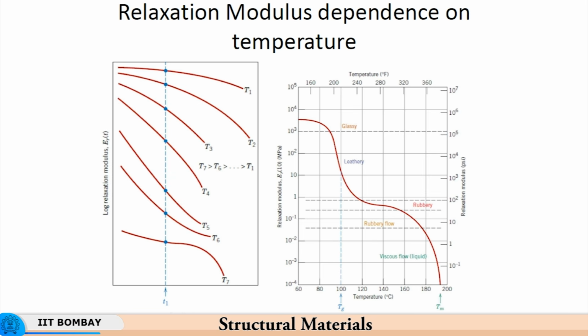with temperature, it tends to come down, but it does not have a relaxation modulus as such, because if at high temperature you deform a metal to a certain strain and hold it at that for a long period of time, there is no time dependent variation in the load. Okay, in metals there is no time dependent variation in the load, but in case of polymers it is there, because you are talking about polymeric chains.